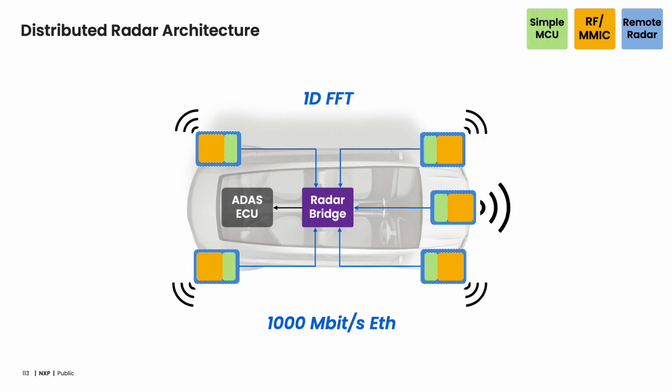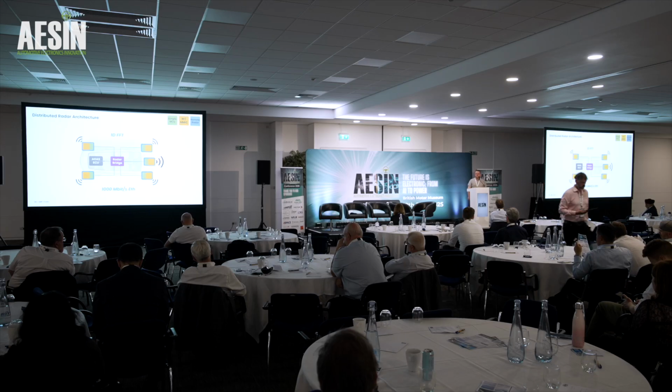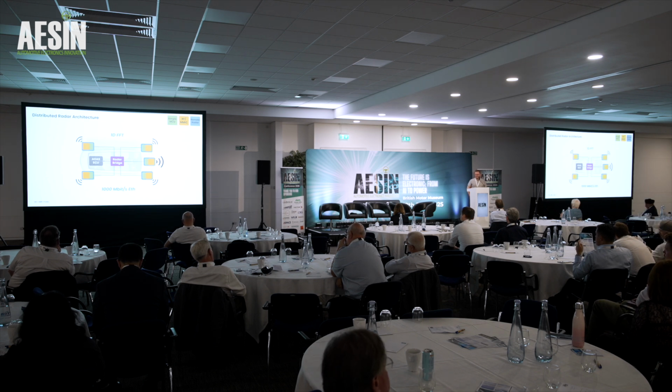So one idea that we have proposed and implemented is to cut the radar signal processing chain after the first stage, the range FFT, 1D FFT. The data rates here for a 4x4 channel radar, as typical you would see in a one-chip radar device, you can accommodate within a 1 gigabit per second Ethernet link. So there is an added cost involved in upgrading that vehicle network to accommodate the higher data rates required, but there are optimizations possible at the edge for that balance.